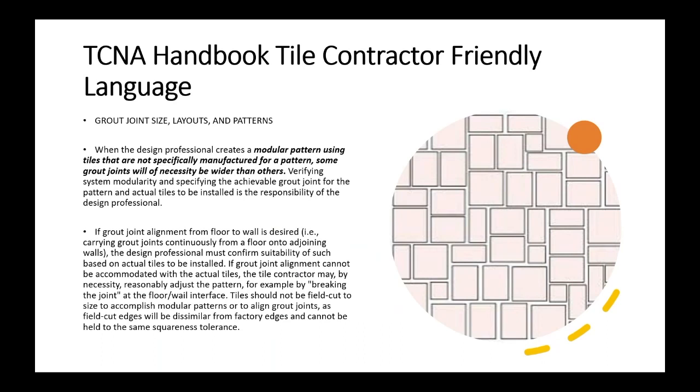And I'll also say I've been on many projects where they buy or want tiles used from different manufacturers. And they expect them all to fit together because in theory, an 8x8 and a 16x16 should line up grout joint size if I put two 8x8s next to the 16x16. But if they're not manufactured to be, number one, calibrated and more precise, the odds are very slim that those grout joints are going to be consistent. And that's really what this is talking about.